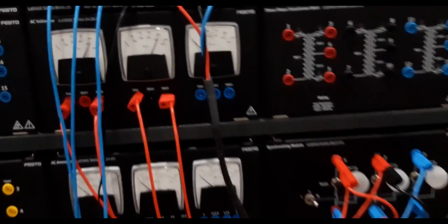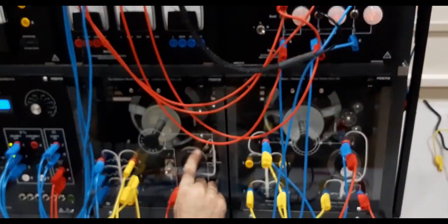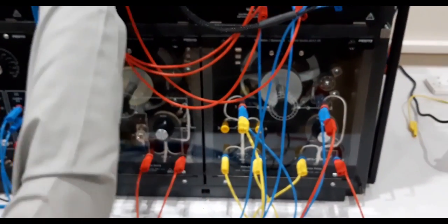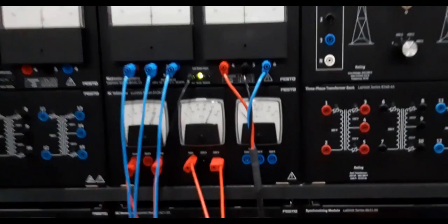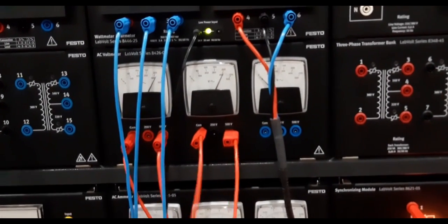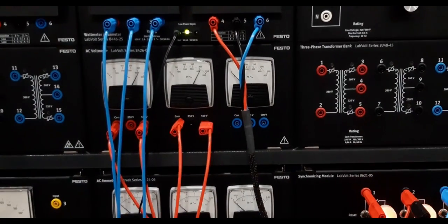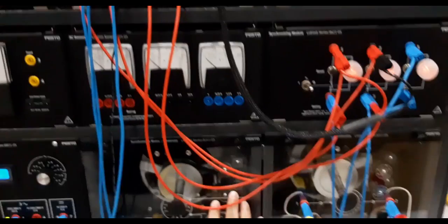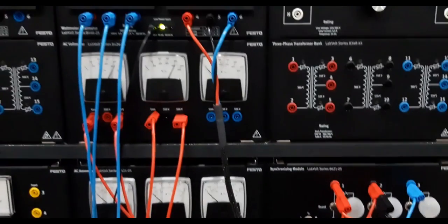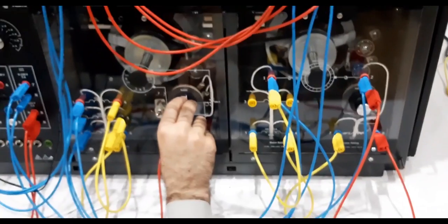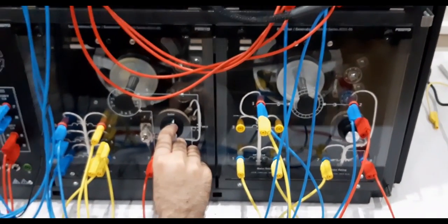Okay, so let me explain even what we were doing actually. We were also changing the field of the main machine, because I mentioned there, if you want to achieve the voltage of the generator close to that of the system voltage, we can also vary the field current. We change this voltage either by increasing the speed, which changes the derivative, or we also change the excitation of the field, the main field, which also changes the flux state. And in these two ways, we basically change this voltage.